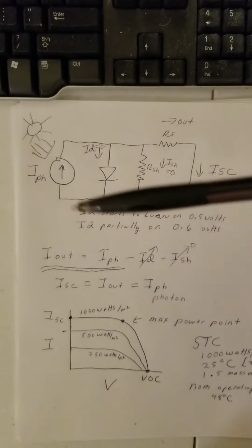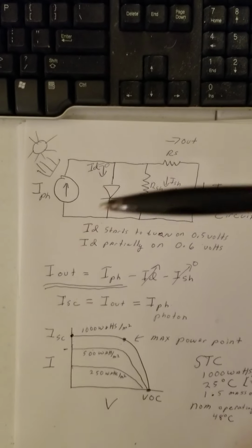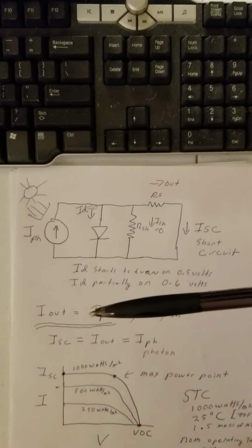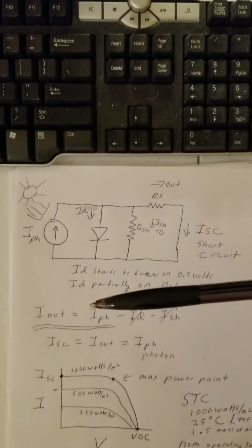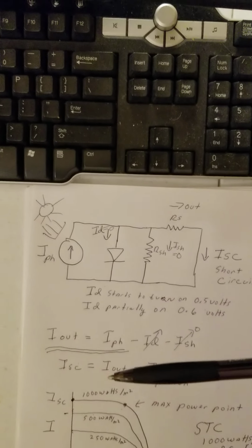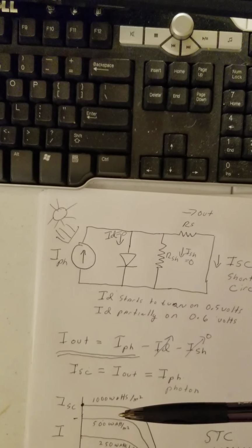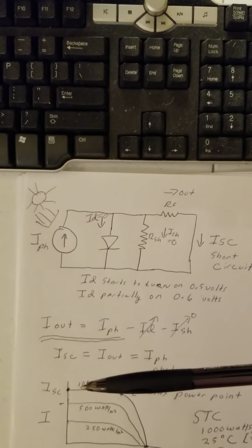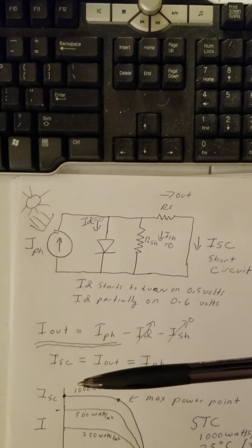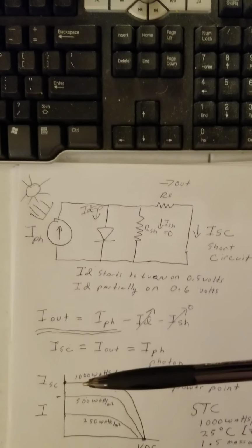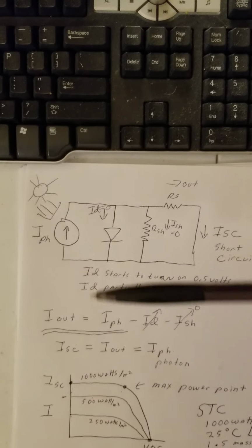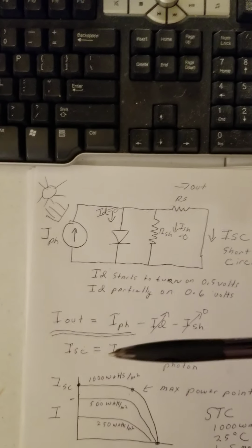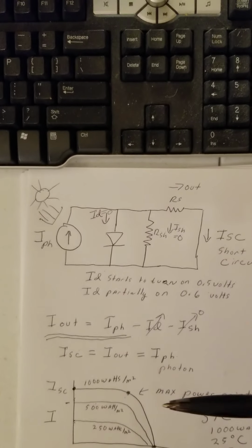Now, if you live in a desert where there's very few clouds and the humidity is very low above the land, you can actually get more than 1,000 watts per meter squared. If you live near a coastline where you have clouds, you can get a whole lot less, and you can get to the point where you get no power out of your solar panel at all.